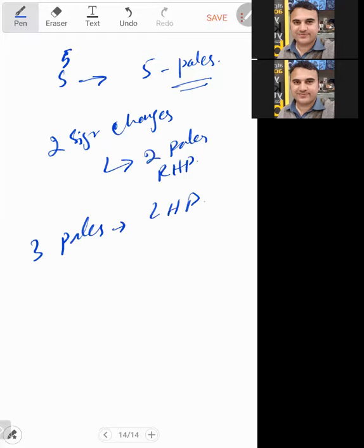So it quickly gives us the analysis of whether it is a stable or unstable system, and the question over here is whether it is a stable or unstable system. Since poles lie in the right half plane, we can say that this is an unstable system for the feedback system. So you see that you can quickly analyze the system.